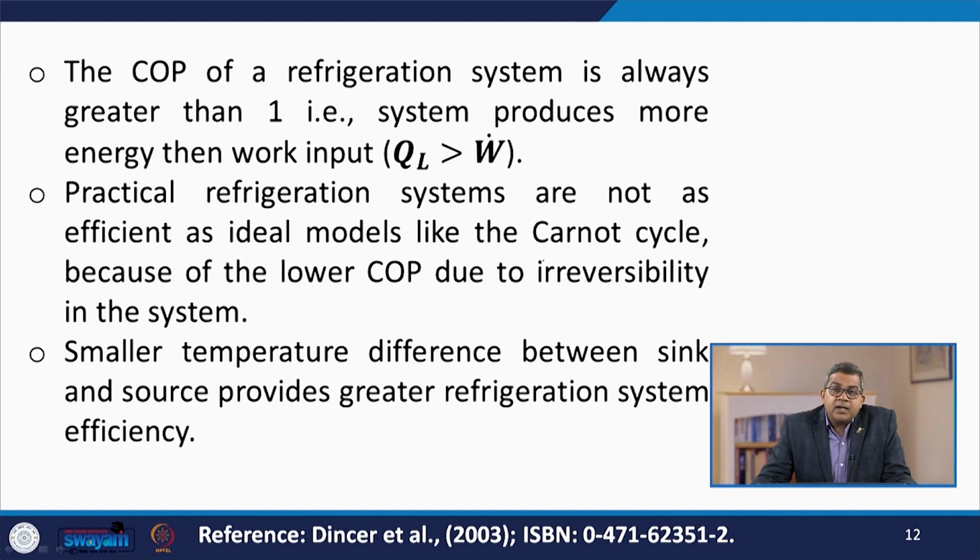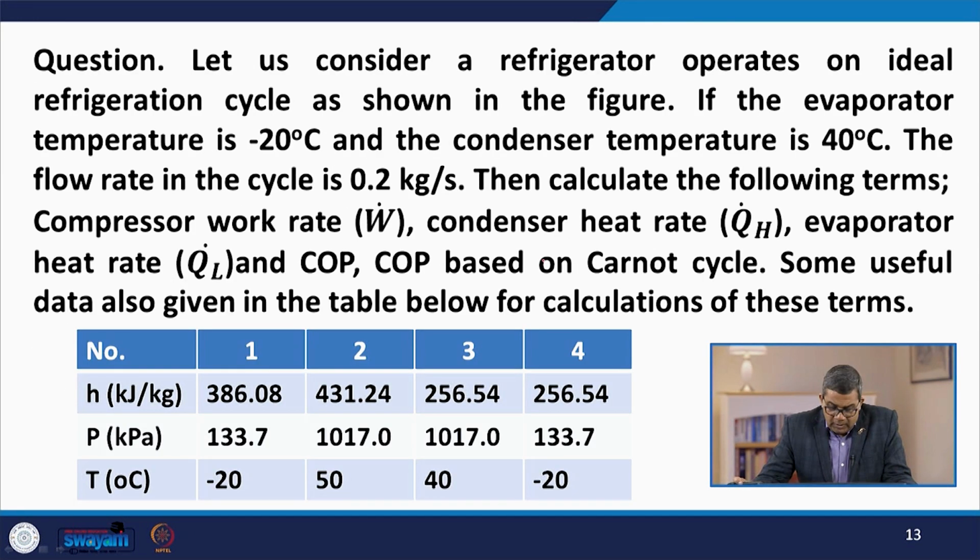The practical refrigeration systems are not as efficient as ideal models like the Carnot cycle, because of the lower coefficient of performance due to irreversibility in the system. A smaller temperature difference between the sink and source provides a greater refrigeration system efficiency. So we discussed this particular theory in detail.